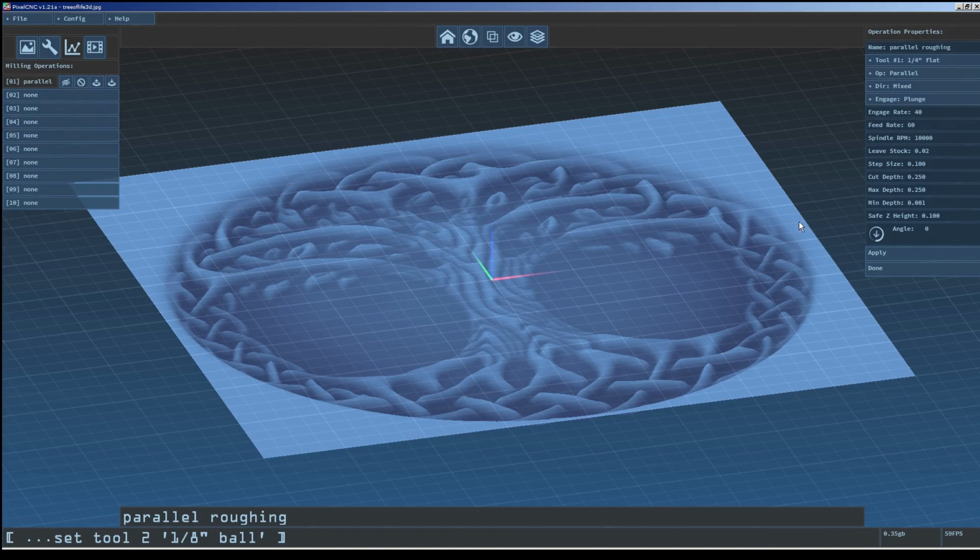This is important for a hobby or tabletop CNC that may not be especially rigid, especially with the decently sized bite our step over will entail. And so for the step size here, we're going to go with 1/10 of an inch, or 100 thou. If this were a finishing pass or we were working with a CNC that is not very strong or powerful, naturally we'd go with something smaller, which would lead to more individual cuts and a longer runtime.